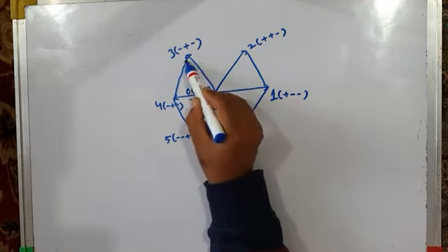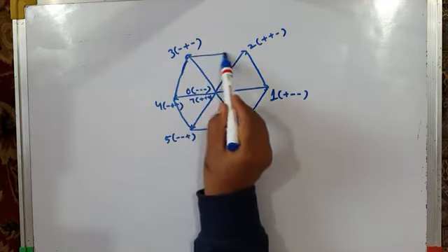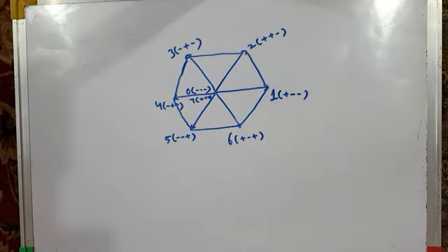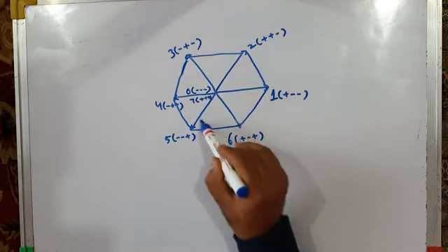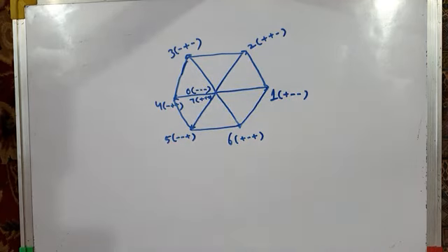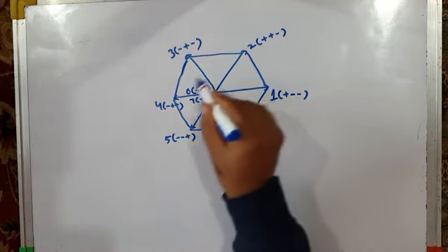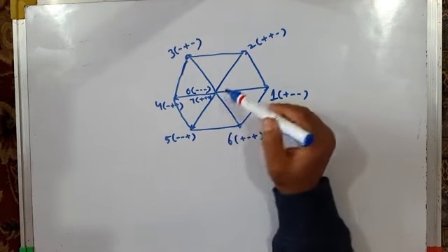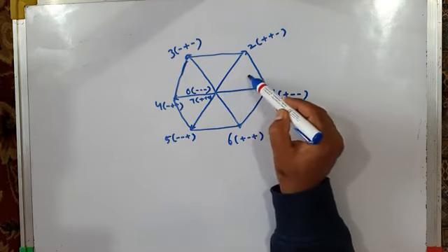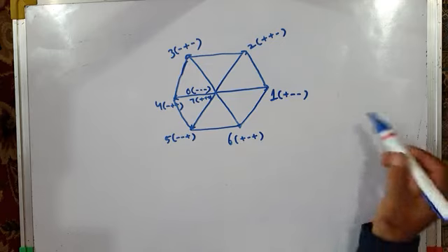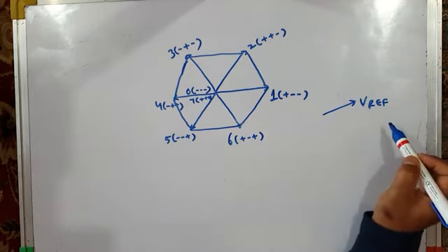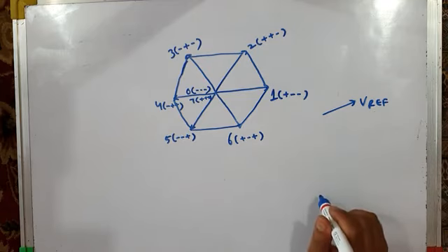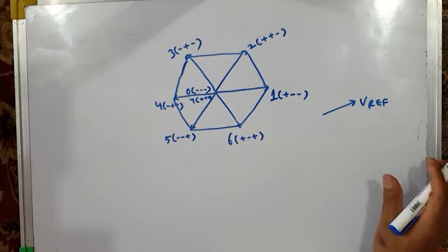So this is the shape of a regular hexagon. And as far as the reference vector is concerned, the reference rotating vector will be rotating within this hexagon, and it will be tracing a circular trajectory. It will be rotating in a circular path. What is the maximum length of this rotating reference vector? Let me tell you the length of rotating reference vector, Vref. It represents the modulation index. Larger the length of rotating reference vector, larger will be the inverter output voltage.